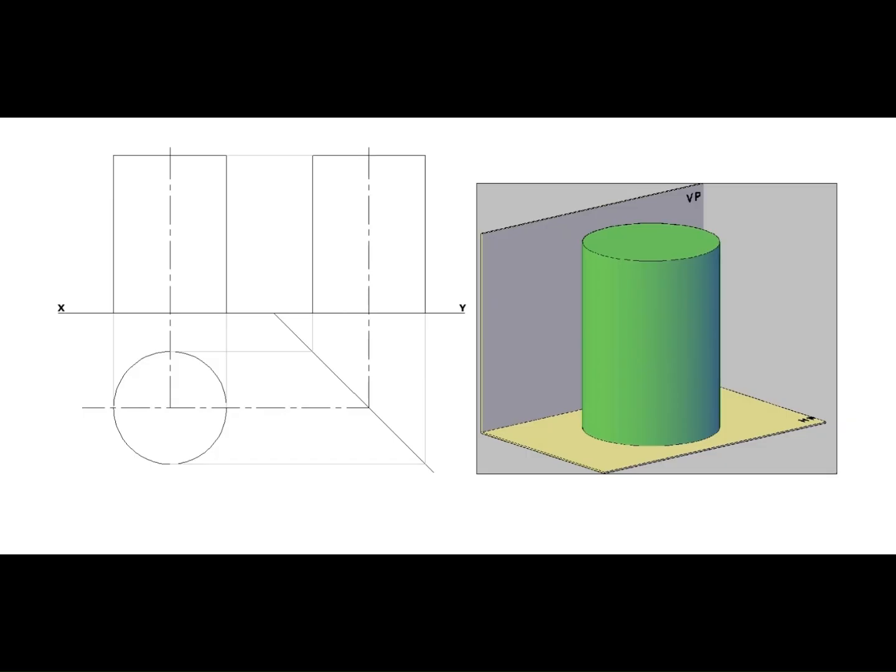These are the three views of a cylinder standing on the ground with its axis perpendicular to the ground. Since the cylinder does not have any base corners or longer edges, divide the circle, that is the plan of the cylinder, into equal number of parts. We can divide that into 8 or 12 equal parts. In this case, we are going to divide that into 8 equal parts. Name these points as 1 to 8.